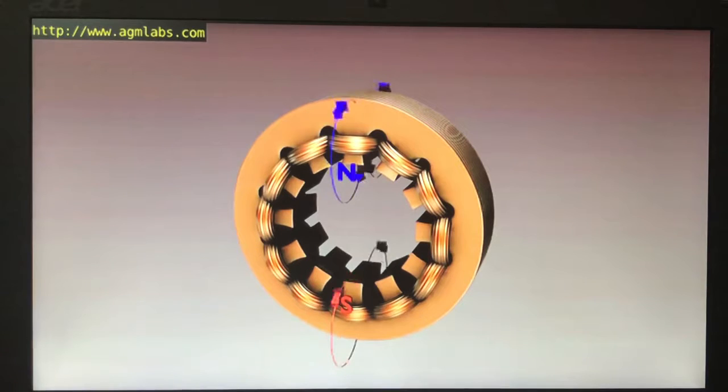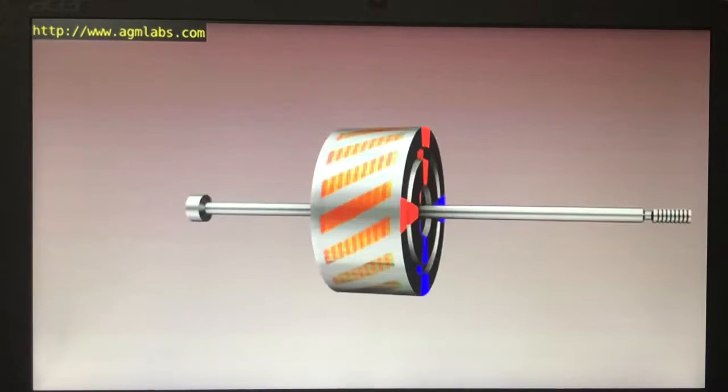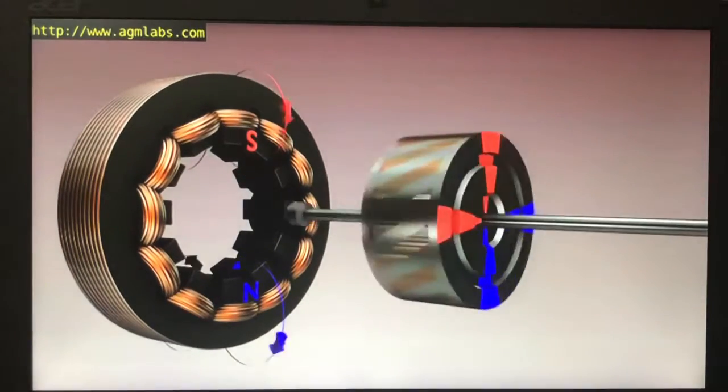When AC power is connected to the coils, a directional flux is created depending on the current's direction and the winding direction of each coil. See in this animation how the magnet's polarity changes every half cycle of the AC power supply, creating an alternating magnetic field. The rotor is the rotating electrical component. It also consists of a group of electromagnets arranged around a cylinder, with the poles facing toward the stator poles. The rotor is located inside the stator.